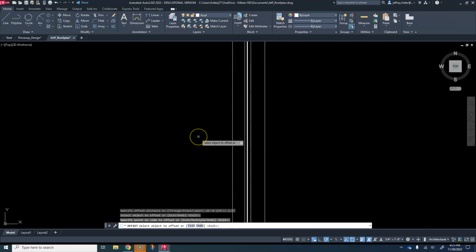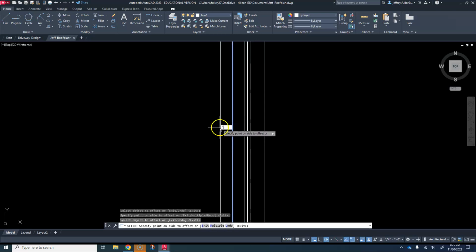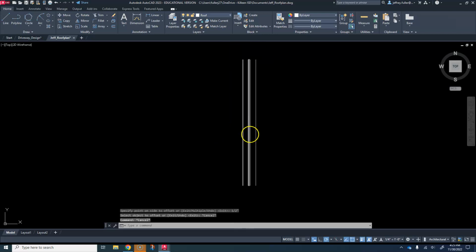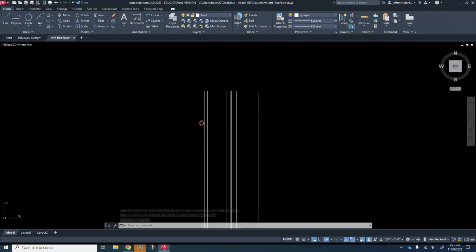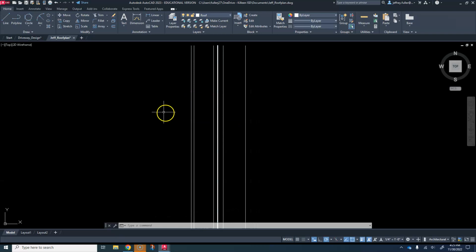And then my offset one more time for my drywall on the inside of the house, that's going to be 1/2 of an inch. All right, so now we got all the different layers. And what we're going to do, so we don't forget what everything is, we're going to go ahead and put our patterns together. So I'm going to go ahead and close off the top.